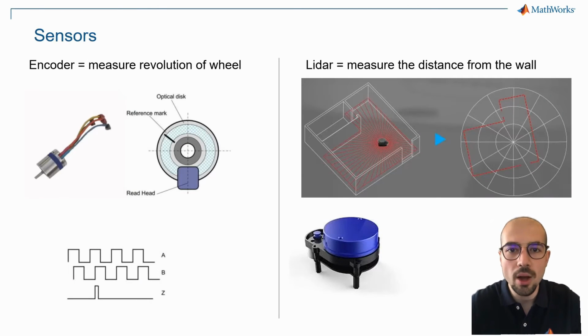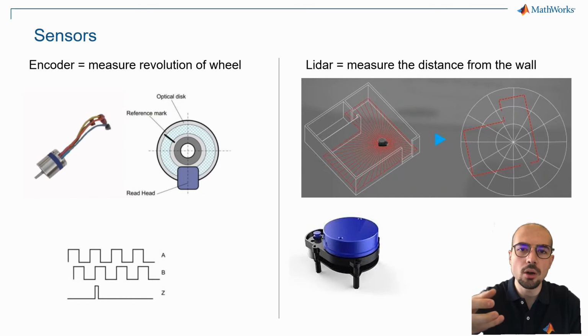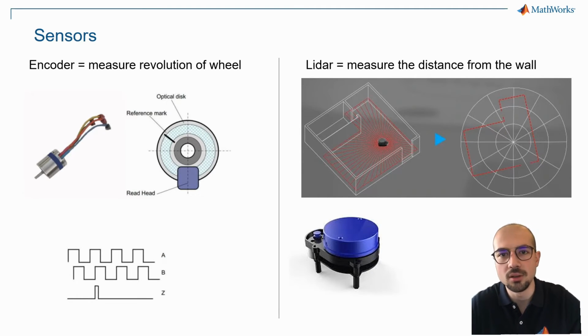Then, in order to acquire information, we are going to use encoders, which are specific hardware to read and know exactly how far and how the wheels are moving. They measure the angle of the wheel, and also a LiDAR. The LiDAR is a particular hardware that acquires distance from objects using a laser, and in particular it can build maps, and as you can see in the picture, know exactly the distance of each point from the center of the laser.